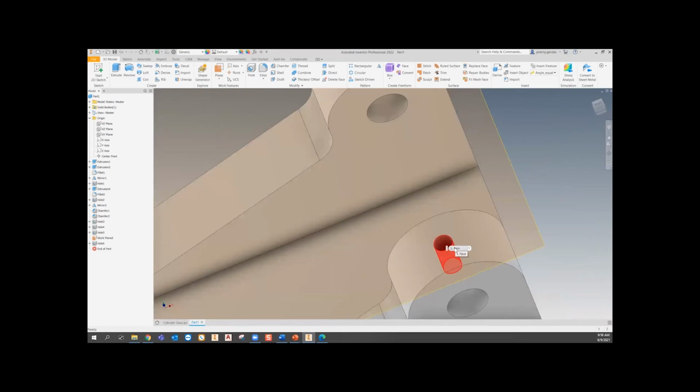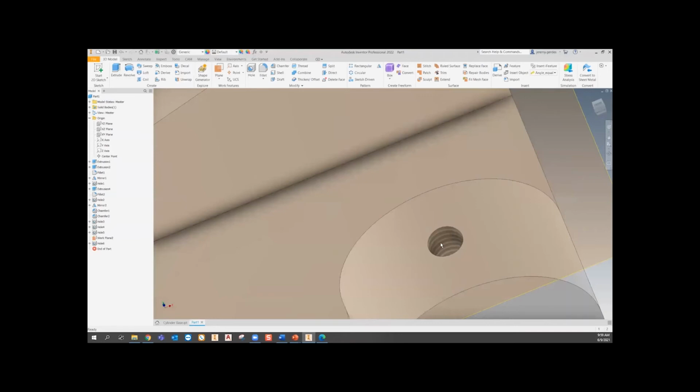And a lot of people ask and say, well, okay, it shows threads, but they're not threads. And you can model 3D threads. I would usually suggest against it unless there is an absolute must or reason, just in the fact that it burns up a lot of the power. When you do this or add threads, the system knows what type of threads they are, and it's able to call them out, and all the geometry form is correct in the model. So even though the representation doesn't give you the actual lips and parts of the threads, they are threads in the system.